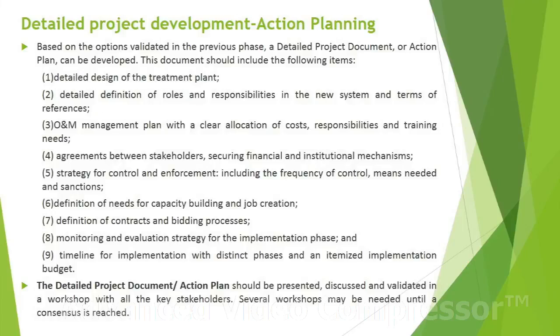Third one, and the most important phase, comes the detailed project development and action planning. Based on the option validated in the previous phase, a detailed project document or action plan can be developed. This document should include the following items. The first one is detailed design of the treatment plant, detailed definition of roles and responsibilities in the new system and the terms of reference, O&M management plan with a clear allocation of costs, responsibilities and training needs,